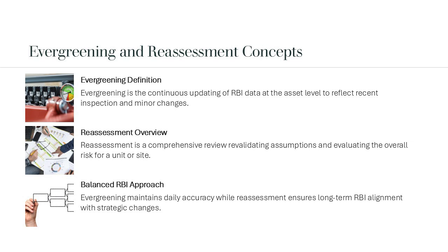Together, evergreening and reassessment provide a balanced approach to RBI maintenance. Evergreening keeps the assessment current on a day-to-day basis, while reassessment ensures long-term validity and alignment with strategic, regulatory, and operational changes. An effective RBI program clearly defines how and when each approach is applied.